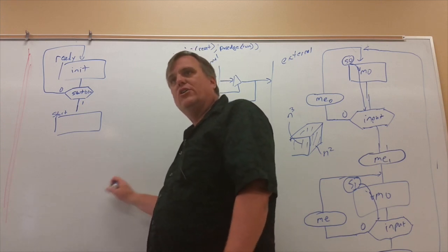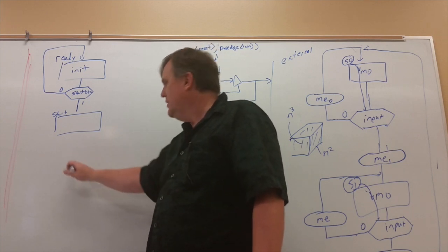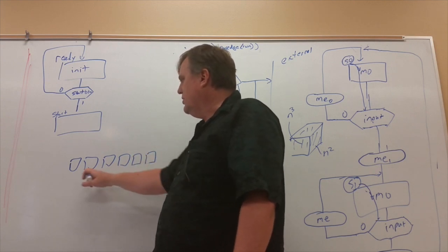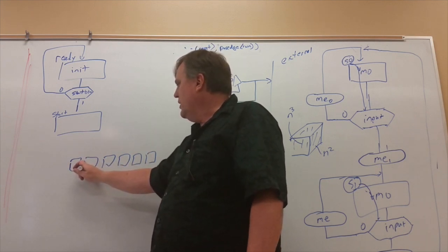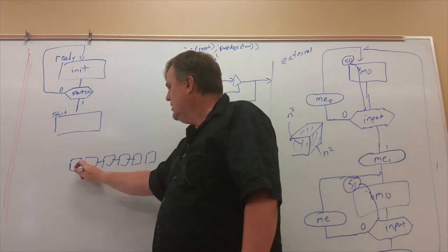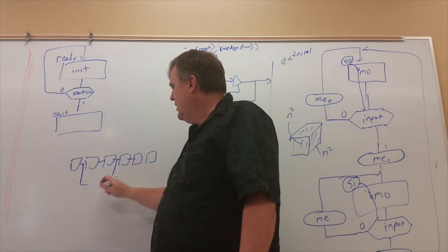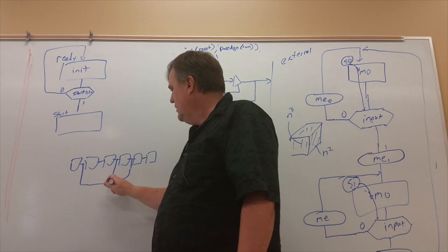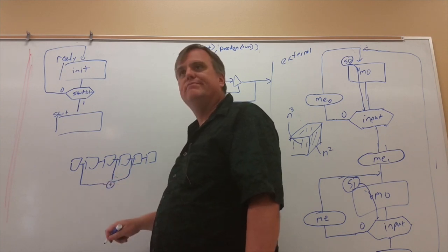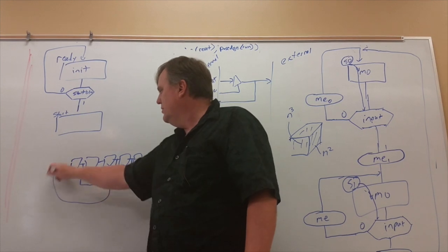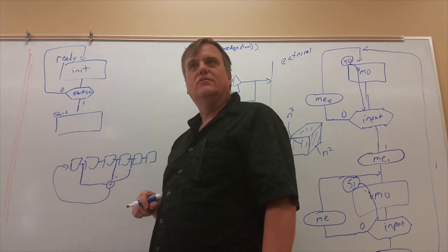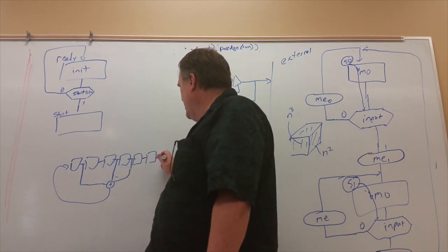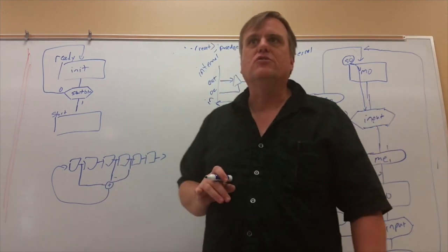They do a calculation based off the value coming out, so they might have a series of bits going through, and they'll take, for instance, the taps between these states, maybe this one, and this one, and this one, and I XOR them all together and use that one to feed back in. And then here's your output bits, and you ask for a certain number of bits.